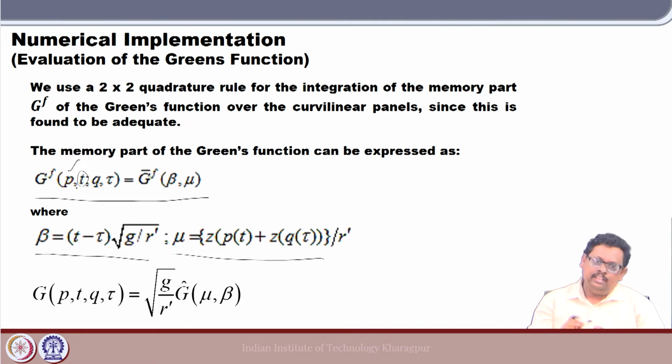Also, we need to consider the impulses that I am giving starting from the 0th second. So, at the 0th second, the first time I put an impulse, and again in the first second I put another one. So, in each second I am going to give one impulse. Now, at the 10th second it is not sufficient to only consider the effect of the 10th second impulse. We need to consider the 9th second, 8th second, 7th second, 6th second, all this combined effect also we need to consider. So, that is what I say here, that p is only a function of t,